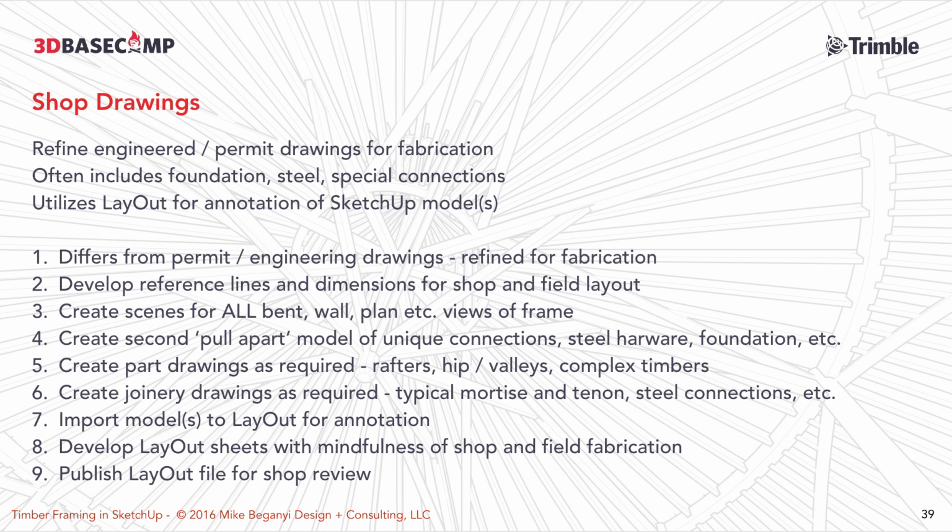So oftentimes I'm adding a lot more dimensions. Depending on who I'm working with, which timber framer or which builder, sometimes that's a lot, sometimes it's not. It really depends on the skill of the people. I've had to actually do a project where I had to do a part drawing of every different rafter because the guys weren't comfortable laying out a rafter based on the roof pitches and the spans between the plate and the purlin or the ridge. So I laid out three different rafters.